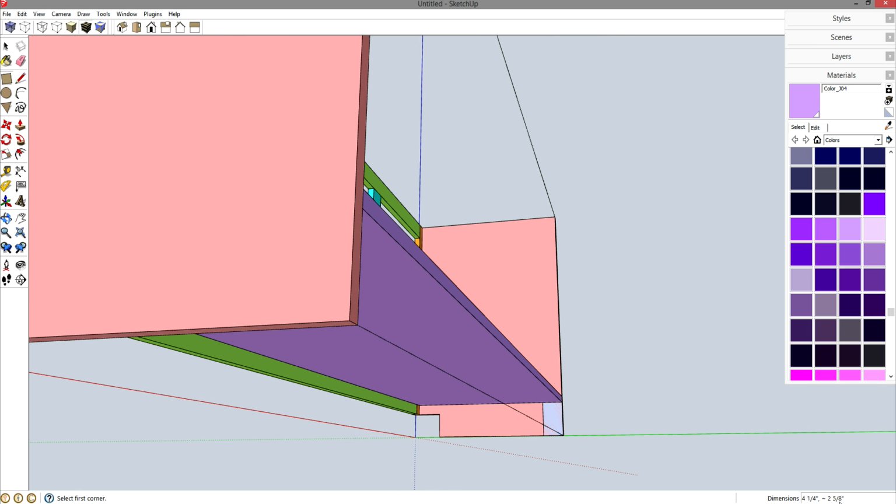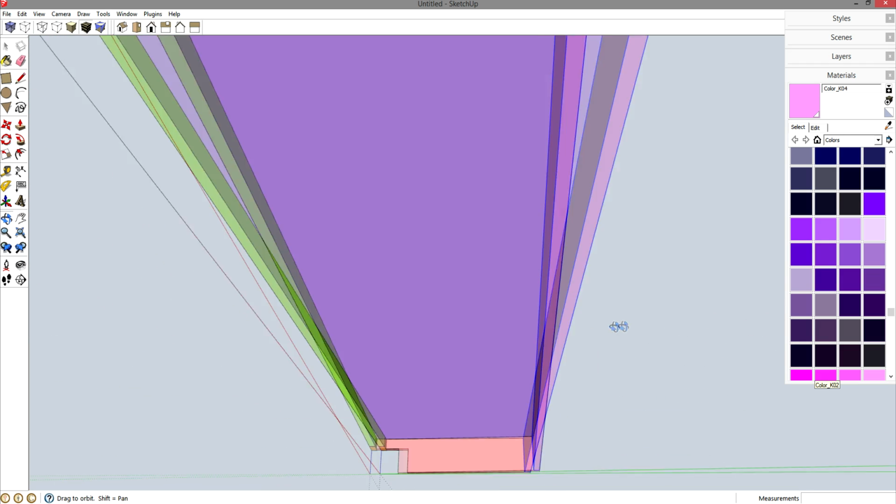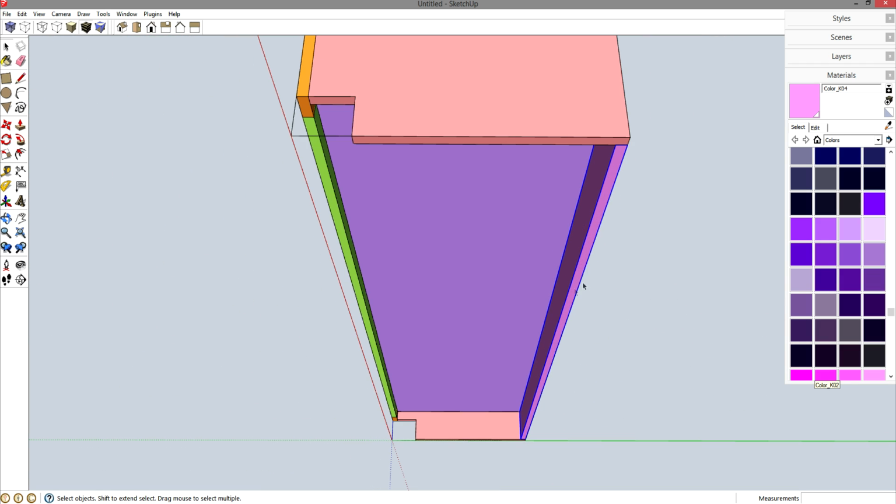My second dimension is the smaller of the two, and I'm just using 3/4 inch plywood. So to only modify the second dimension, I'll press comma, 0.75, enter. P4 push pull. Let's pull this all the way over here to this corner. Space bar, triple click, G4 component, enter. Now let's drop another color on top of that, just to distinguish parts.